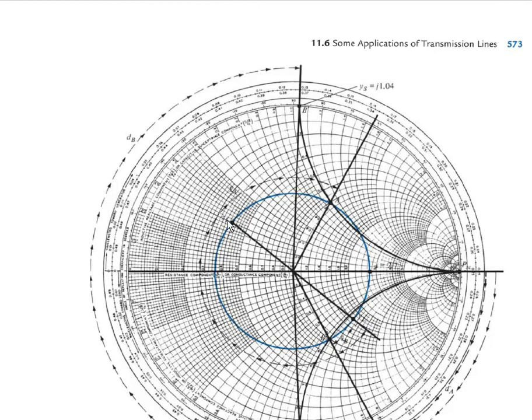Then this straight line we can extend just opposite to that circle. So from this point P to O, then O to P dash we can extend. This point is ZL, the normalized impedance, and the extended point will meet this blue circle, and that point is YL, the normalized admittance. Now all the calculations are based on this normalized admittance. So now we found the normalized admittance.